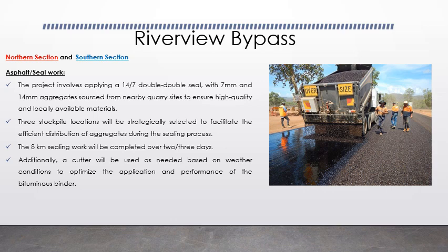Additionally, to optimize the application and performance of the bituminous binder, a cutter will be used as needed based on weather conditions. This flexibility ensures that the sealant adheres properly and performs well regardless of environmental factors.